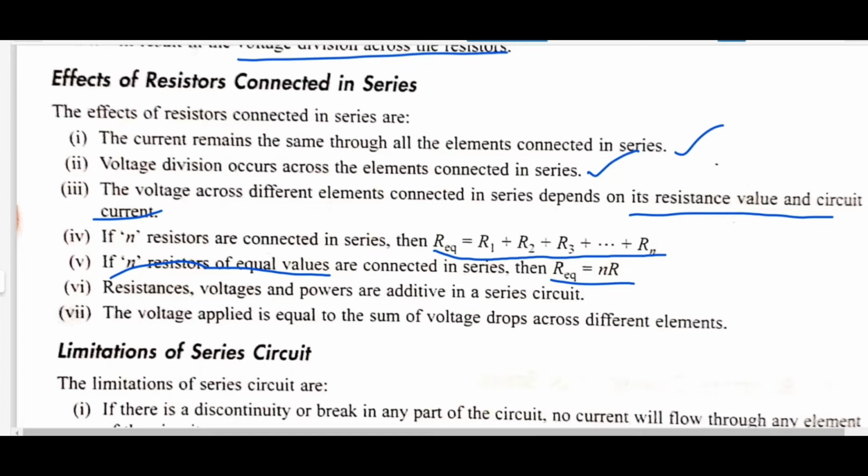Resistance, voltage and power are additive in a series circuit. This is a very important point. You have to keep it in your mind. Resistance, voltages and powers are additive in a series circuit. The voltage applied is equal to the sum of voltage drops across the different elements.